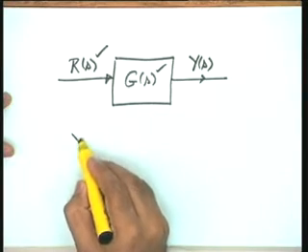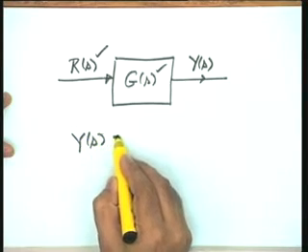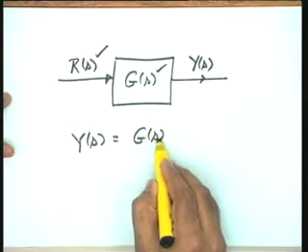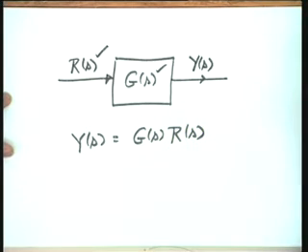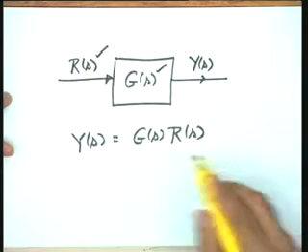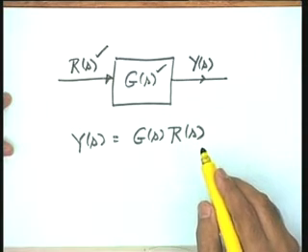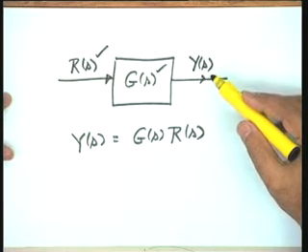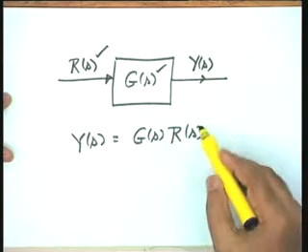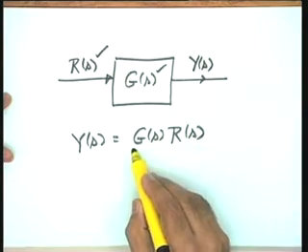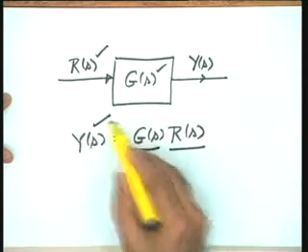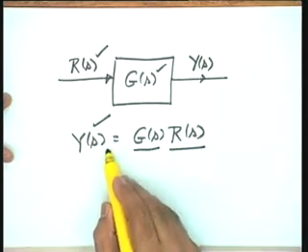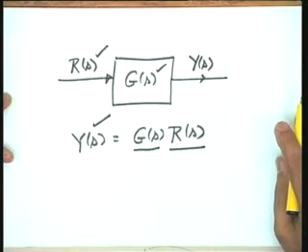So, as such the output becomes Y(s) equal to G(s)R(s), that is in the Laplace domain the convolution is transformed to an algebraic relationship. Now, the dynamic response, that is the output y(t), if I am interested in, I will get first the value of G(s), then the value of R(s), therefrom the value of Y(s), inversion of Y(s) will give me the value of y(t).